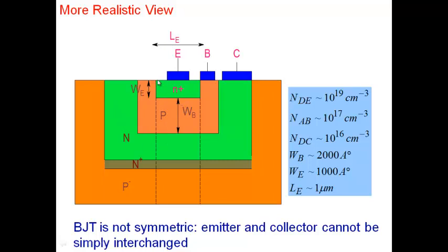And if you note, the emitter has a certain length, and the thickness of the emitter region here. These are usually very small. Similarly, thickness of the base is usually very small here. And this N plus layer is needed because as the electrons are injected, they travel across the base, reach the collector here, but the contact is over here, so the current has to travel all the way to the contact. And you don't want series resistance here, so as the electrons travel, they will see a lot of resistance, and therefore you put an N plus layer here. So the electrons, once they enter the collector, go into the N plus. It provides a low resistance path directly here, and then it goes up here.